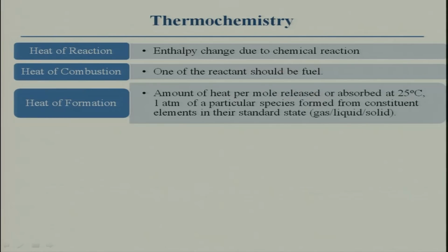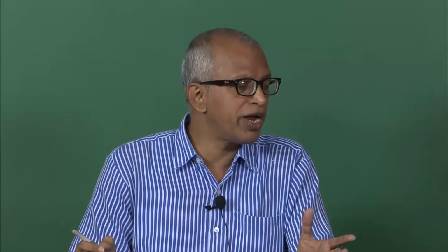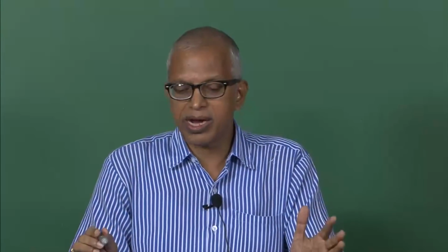But heat of combustion generally, not all the time, because in some books you may find heat of combustion also given as negative, okay. So, generally we assume it to be positive, in our calculations we will be using it as positive all the time, because we take the modulus of the heat of reaction divided by either the moles or the mass of the fuel, right.